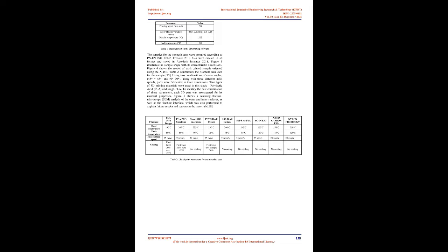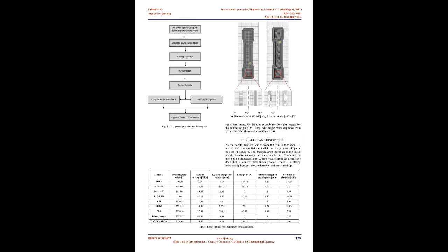2. Methodology. An object is manufactured by fused deposition modeling, FDM, by fusing layers of material in a pattern. Extrusion is usually performed just above the glass transition temperature, then successive layers are added to create the object. FDM 3D printers utilize plastic filament pushed through a hot end, melted, and then deposited in layers on the print bed. Throughout the print, layers are fused, and eventually, they will form the finished part.